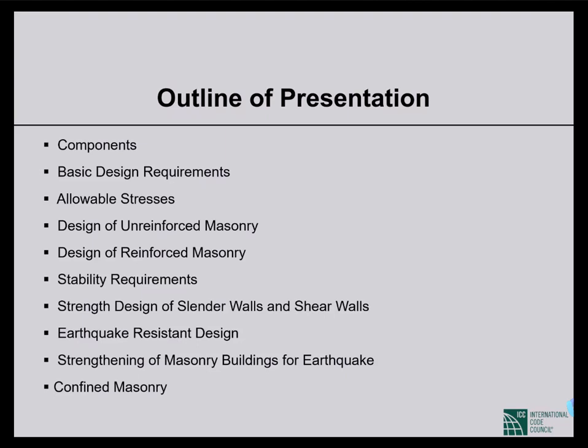So in masonry construction, you want to understand what portion of external load will be carried by the external walls and what portion will be carried by the internal walls. If that is your question, then we usually go with the tributary approach, both for gravity load and lateral load.